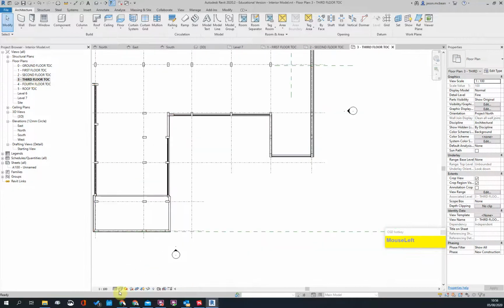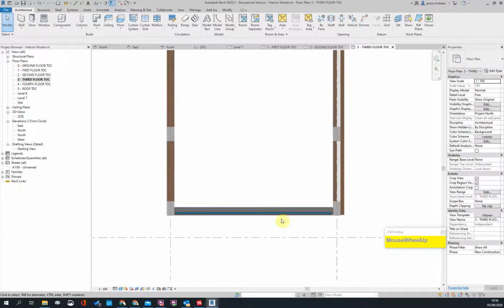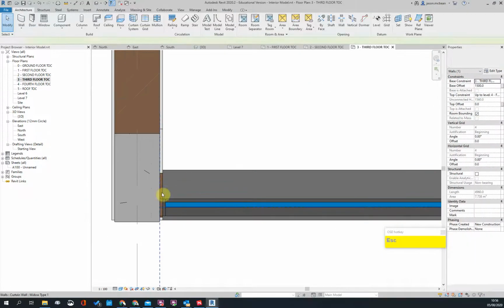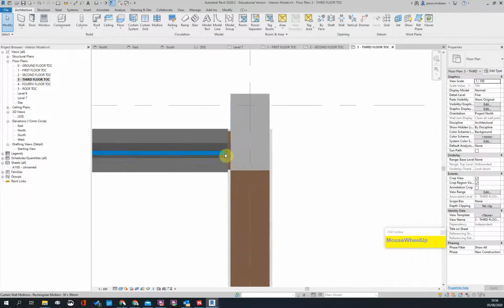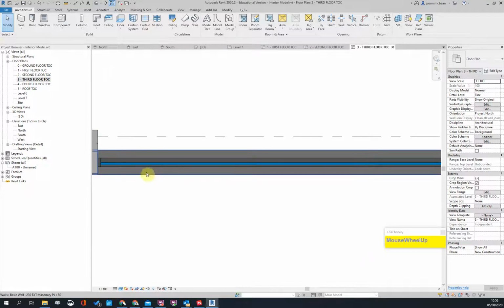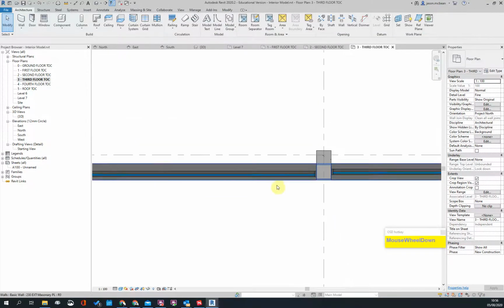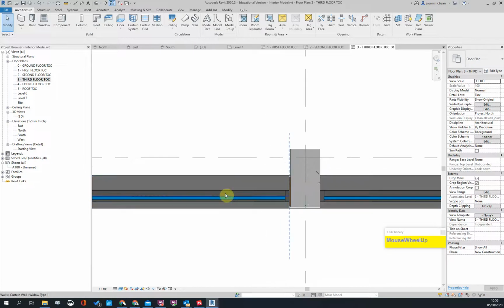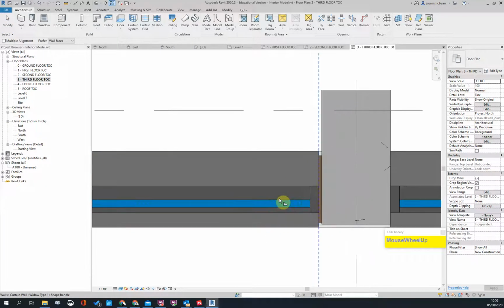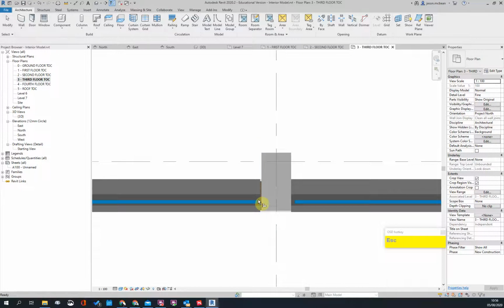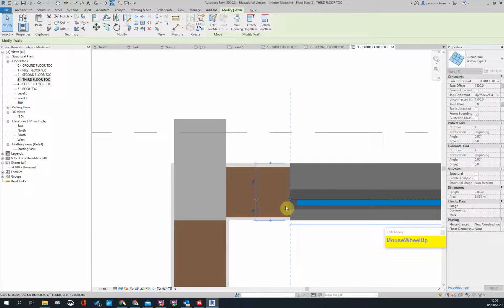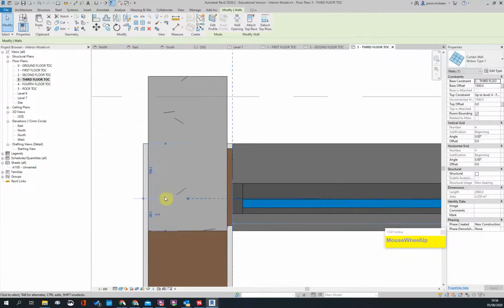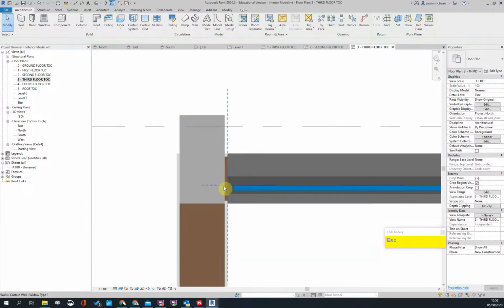So here I'm going to say fine, I'm going to switch on shaded. Okay. Yeah, so I've got a shop front over here. Okay, just remember, make sure it's facing exterior. Generally, these things are offset from the exterior side of the wall by a certain amount. So we'll need to establish that amount as well. Again, I'm going to make sure I align all of these together. So this is important. Okay, so when a shop front, here it will be offset by a certain amount. Here you see it's leaving that line for me, which is correct.